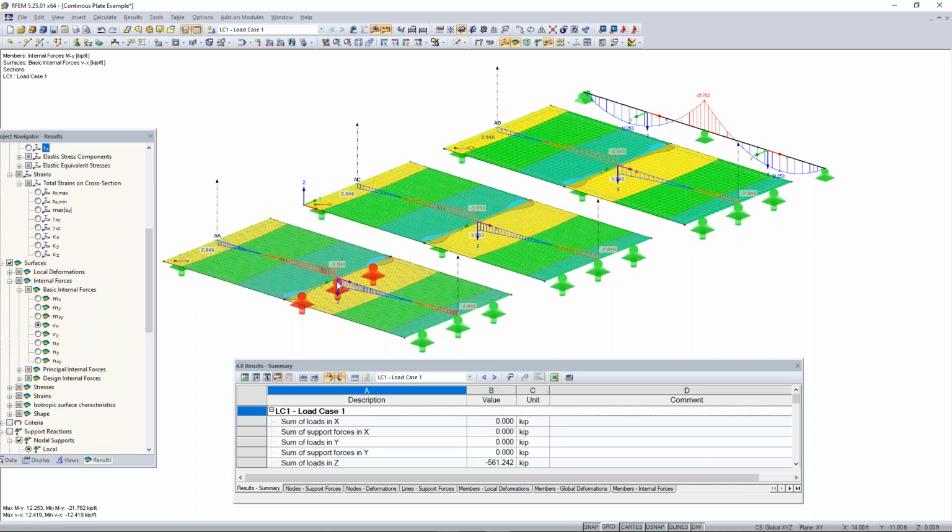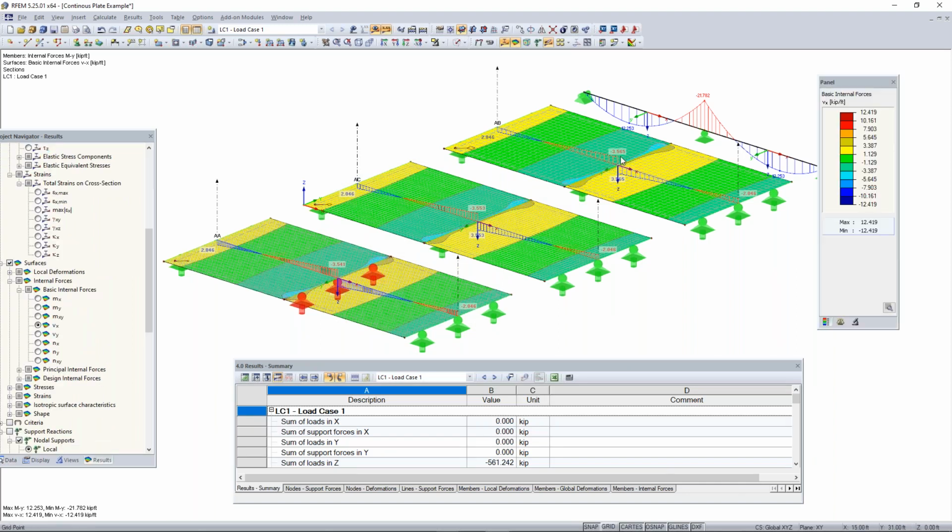You can see that we're actually now getting lower shear forces in our plates. So before we were getting something like negative 3.8, and now we're getting forces like 3.5. And you can also see how the results differ between these two plates with the different FE mesh element lengths.